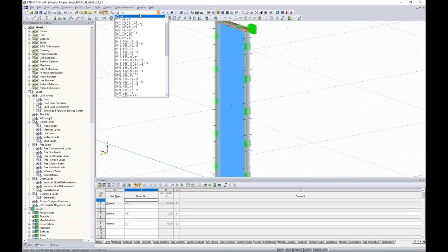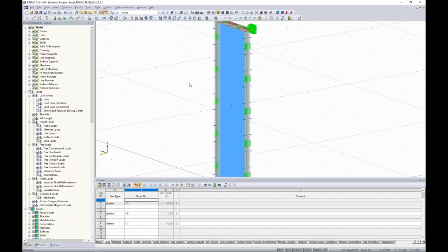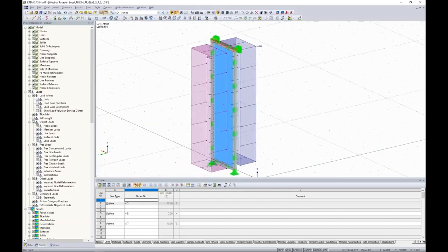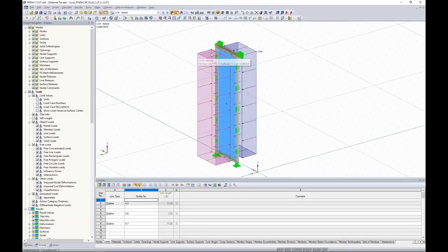And even further, you can take a look at the applied loads. We have the temperature loads, the atmospheric pressure shown here. So again, I've applied 50% to the external, 50% to the internal. You can vary this how you see fit, but this is what the program's coming up with for those gas pressures applied to the surface, applied to the solid elements based on those calculations. Same thing with altitude as well. So kind of interesting seeing what's going on behind the scenes with a local calculation.